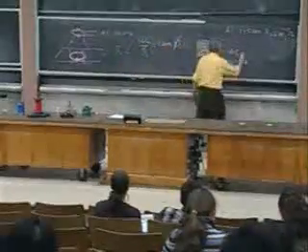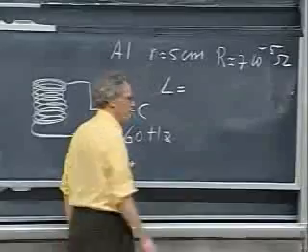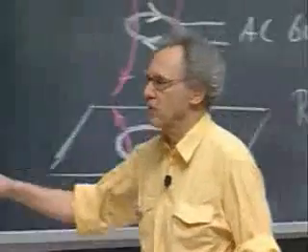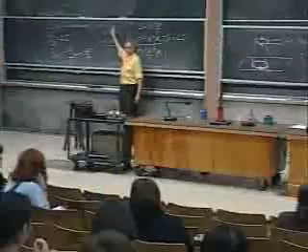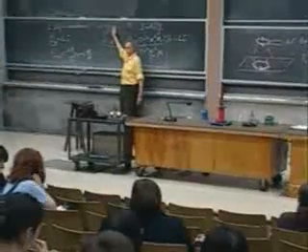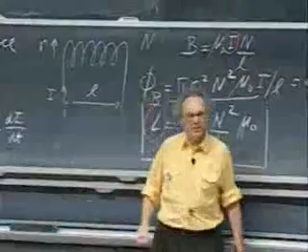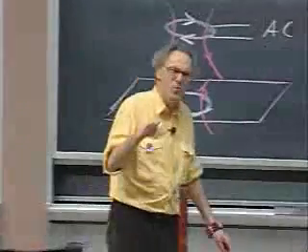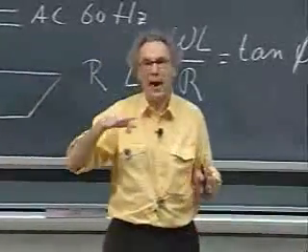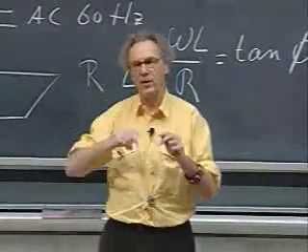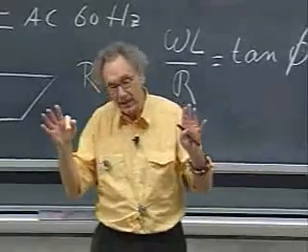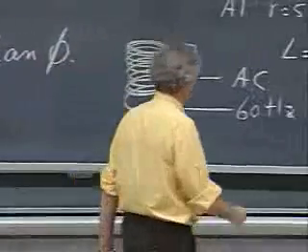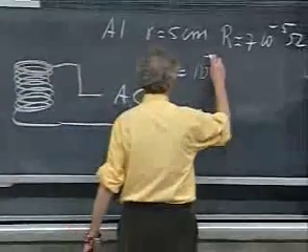I can also calculate very roughly what the self-inductance is of that ring. Now, that's not so easy. Because here, when I calculated the self-inductance, the magnetic field was constant. I assumed it was constant, uniform inside. That's not the case when you have a ring. You have a dipole field. However, I just assumed that the magnetic field was the same everywhere at the surface of the ring. And with that assumption, admittedly I could be off maybe by 20 or 30%. With that assumption, I find that the self-inductance is 10 to the minus 7 Henry.